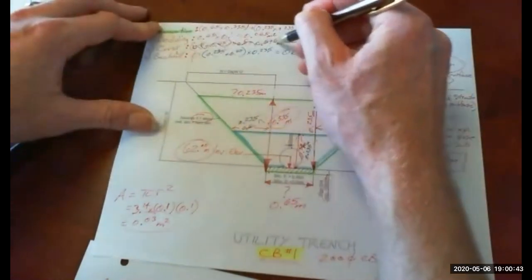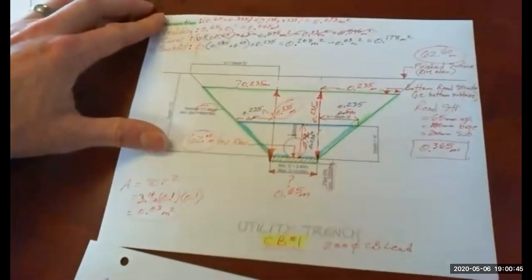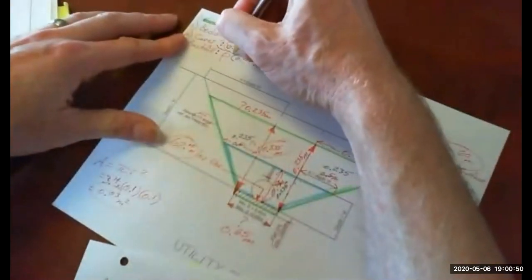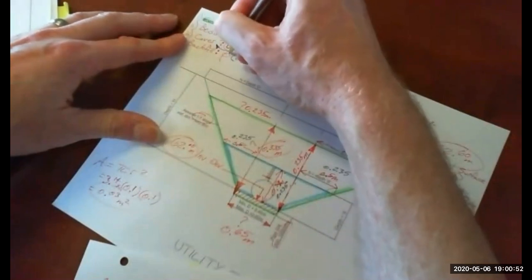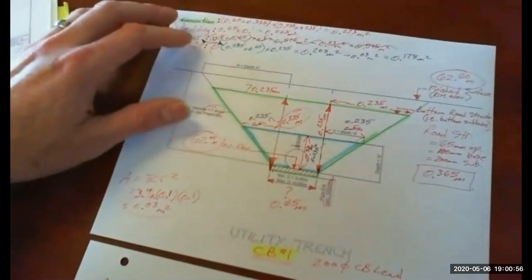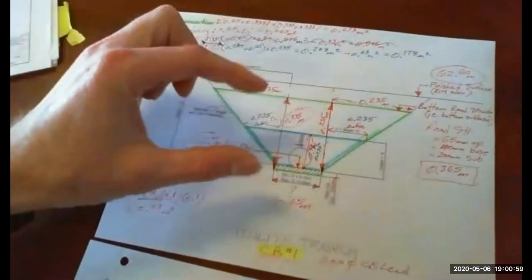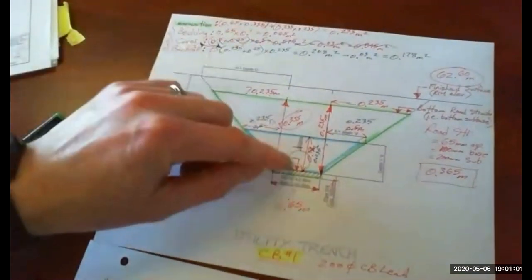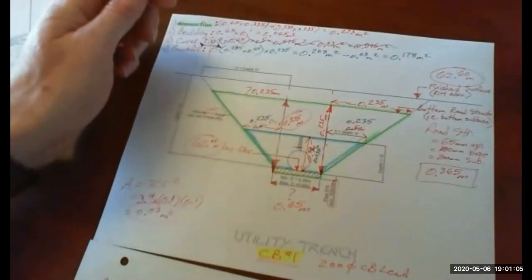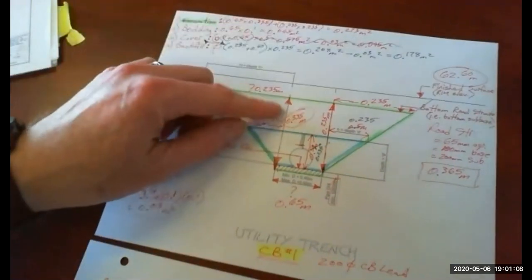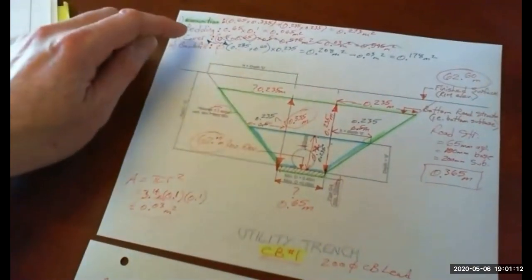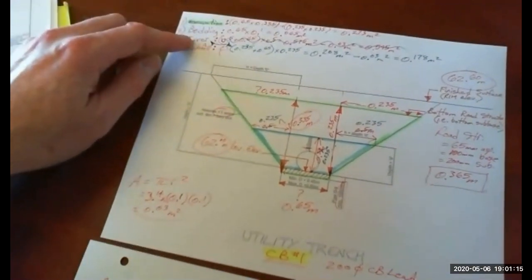So this one here is wrong. So if I draw an arrow here, that's the cover calculation. It's like this because our depth of bury for the pipe is so shallow under the subbase. So no backfill, it's all cover material.